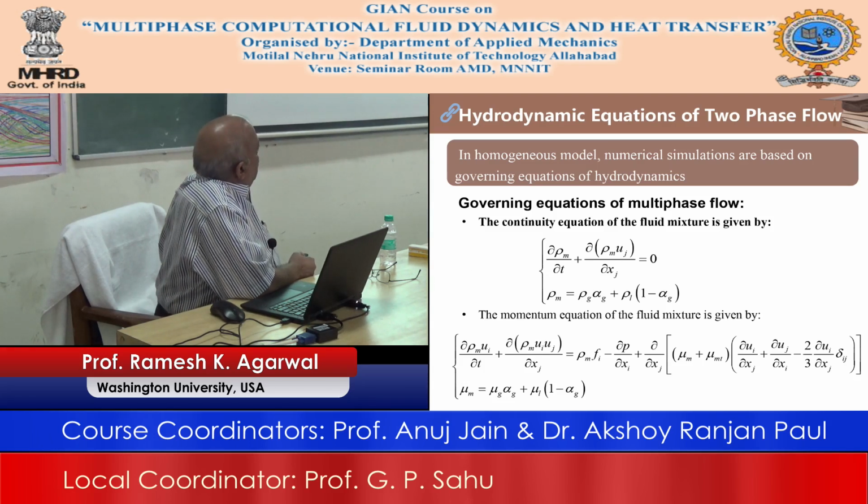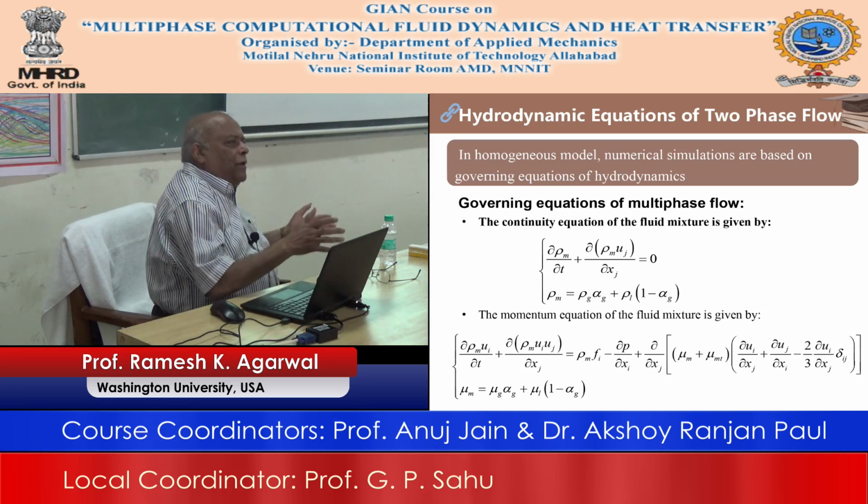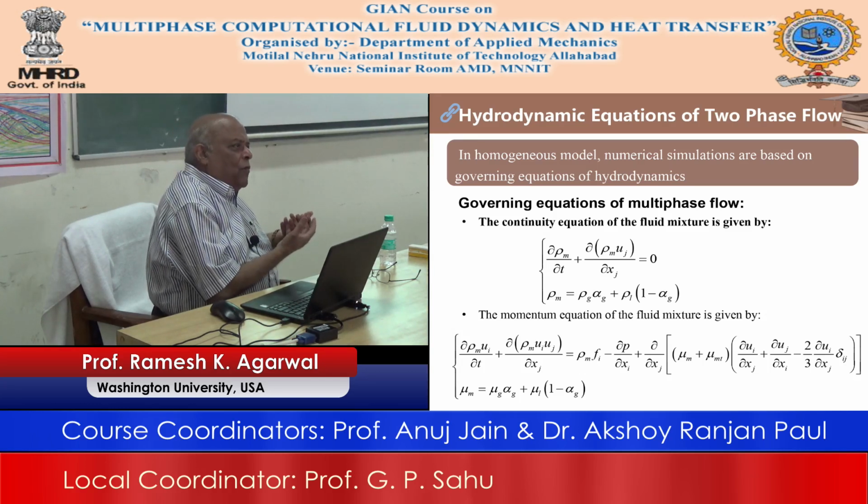The source term is put in because we want to account for some additional effect, and that is that the air bubble can condense or it can evaporate. If you want to model that, then you need the source term. If the air bubble is not going to evaporate or condense, then you don't have a source.